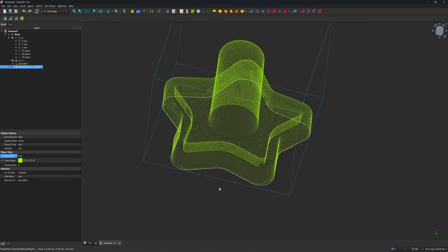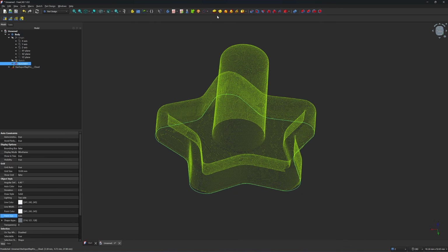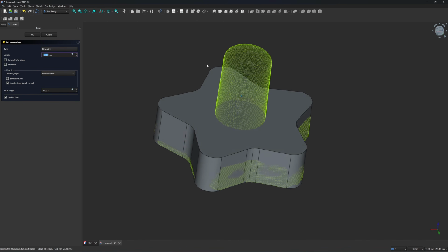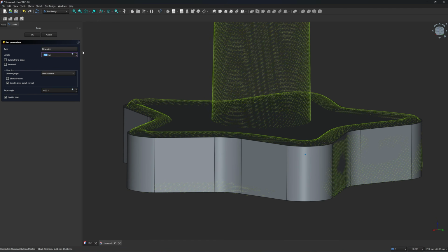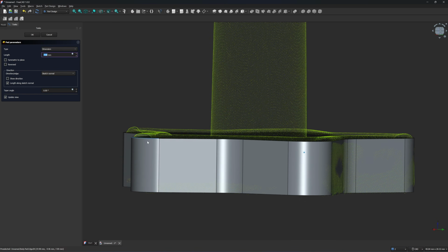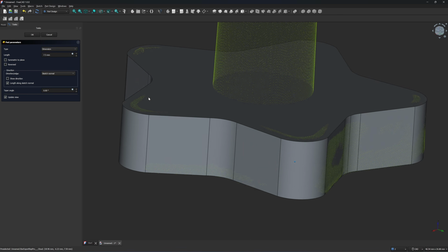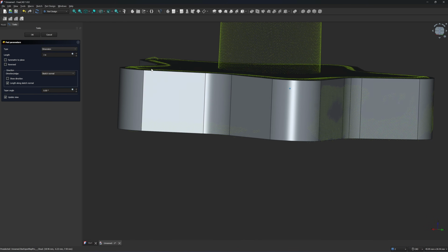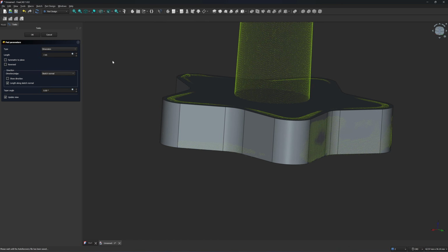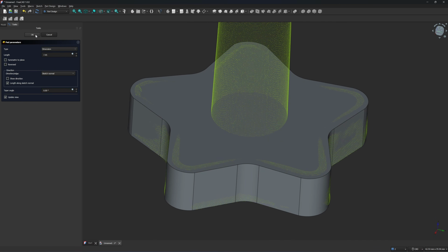Okay, next I'm going to extrude it. And to do that, click on the sketch that we just made. Click on here, path. The command name is path. Click on path. Next you are going to change the height. See here, you're going to change it until it touches the top of the point cloud. I would say 7.5. Okay, 7.5 will be the number. Let's try 7.4. Okay, 7.4, 7.45. Okay, 7.45 will be the actual dimension of this object. I'm going to click on OK.